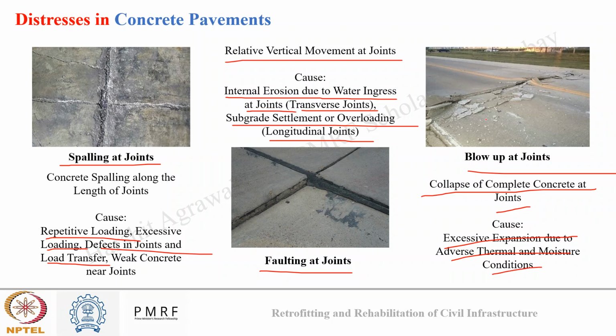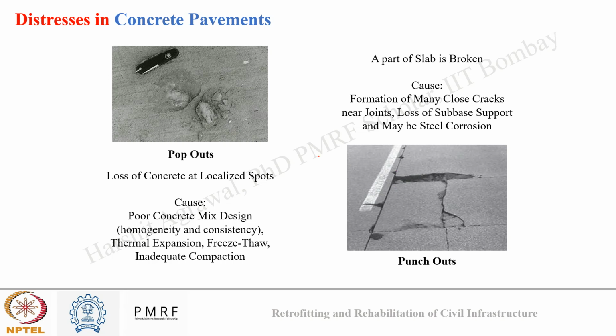Okay, so when there is a lot of thermal expansion within the concrete, such kind of blow ups can occur near the joints if the joint spacing is not provided adequately. Then we have pop outs, which are localized damage in concrete.